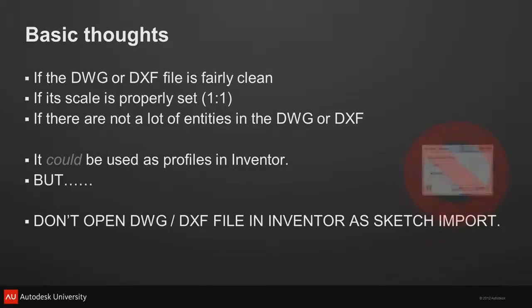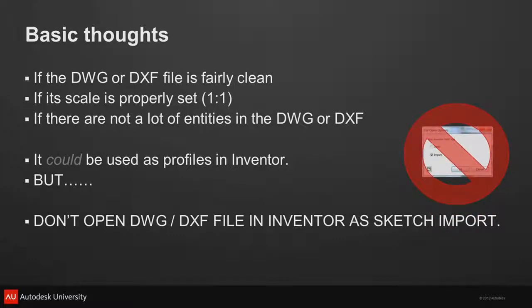It could be used. But the rule of thumb, and I'm probably going to make a lot of the Autodesk development guys, at least the Inventor guys, upset: don't use import. The DWG importer, just don't, okay? Resist it. It's going to cause you all kinds of headaches. It's just hard to use. Don't do it. So I'll show you a little better way to do it.